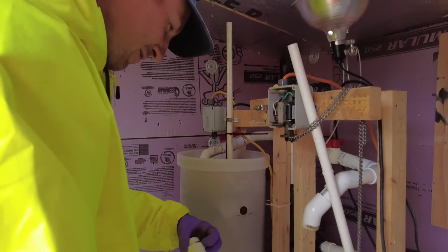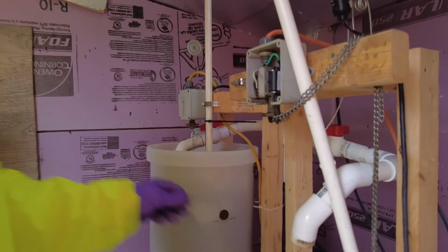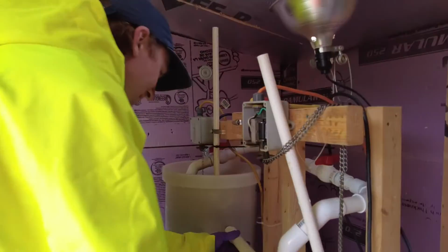With innovative alternative septic systems, you have inspections and you have samples. What's the difference? Well, a sample is pretty simple. You're going out there to sample, and you might do that before you go out to inspect, because when you inspect, you're also probably looking for adjustments you might have to make, and the sampling would inform that adjustment that you would make.